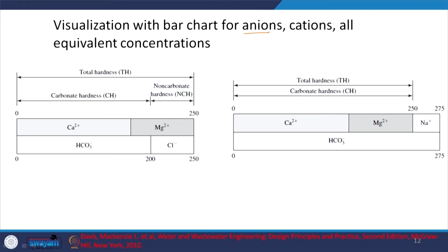So, I have different anions and cations. In this aspect, obviously if I want to use or present them in a bar chart, I can't just have milligrams of calcium, milligrams of Cl-, right. Then there is no way to compare the equivalents. So, here we are talking about charge, and in water always you are going to have charge neutrality, as in all the cations present are going to be equal to the equivalent concentrations of all the anions present. Equivalents of all the cations equal to the equivalents of all the anions. That is the charge balance. There will never be charge imbalance, let us say, right.